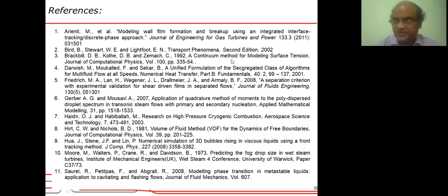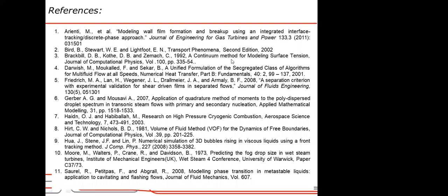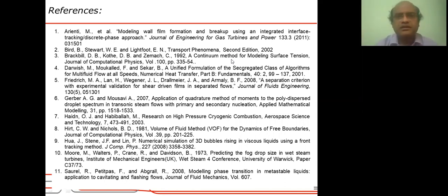Yes, this is what I mentioned about problems involving MHD, magnetohydrodynamics. For example, in the flow of a conducting liquid under the influence of a magnetic field, when there is a liquid flow with ions, charged particles in it, it is like a current. If there is a magnetic field around it, it is like current flowing through a magnetic field. It will induce a force called the Lorentz force. That is added as a source term into the momentum equation. So yes, they are also added in problems involving magnetohydrodynamics. You are right. Clear?